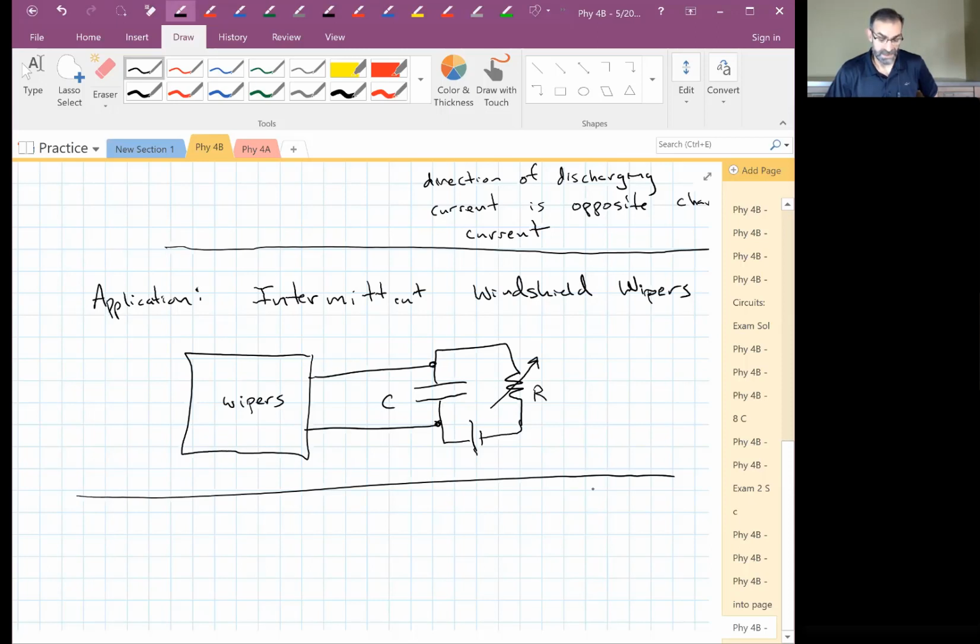Oh, because it's not discharging through the resistor. So this resistor is large, and it gives you a long time constant. Because you're charging through the resistor, but you're discharging through another mechanism that doesn't have that. It takes the current very quickly and releases the motor.